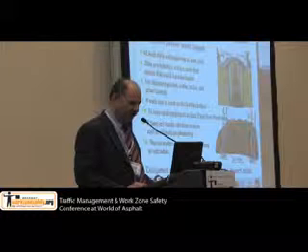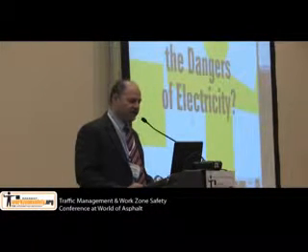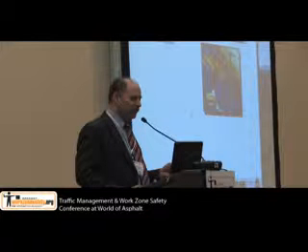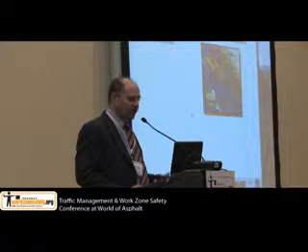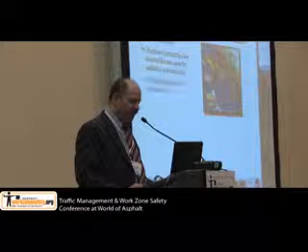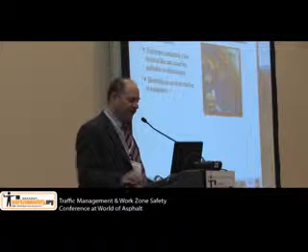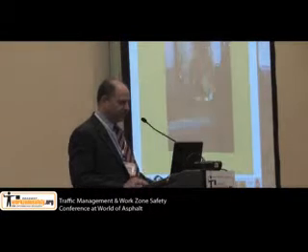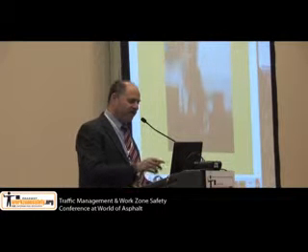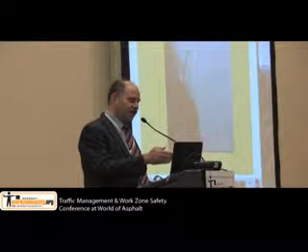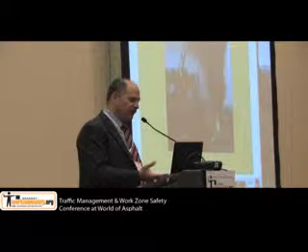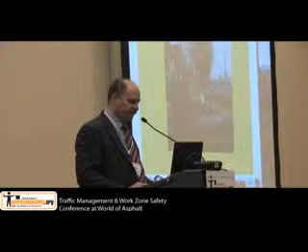I'll briefly go over another one, electrical hazards. A number of workers every year in road construction get killed, primarily from contact with an overhead power line. So we show you, for example, this video that was done by OSHA showing a power line contact. You can see that the drop line from this crane is touching the power line, and as a result, you can see the outriggers are catching on fire.